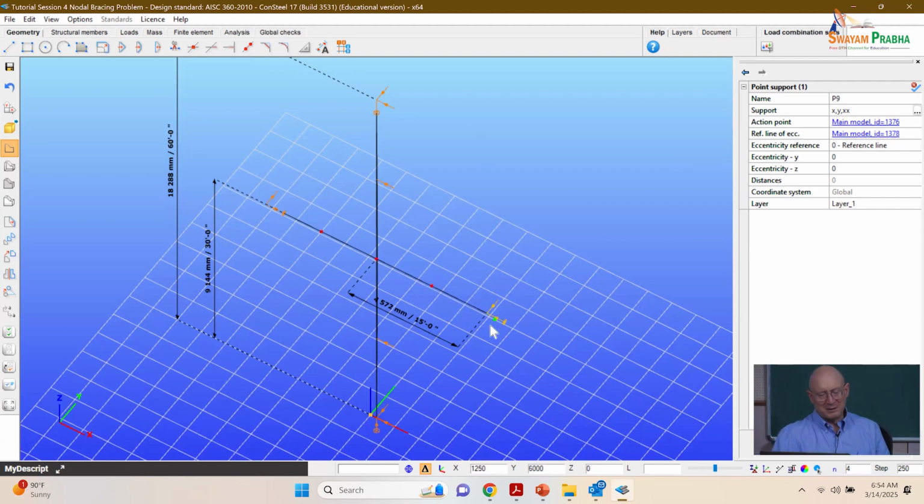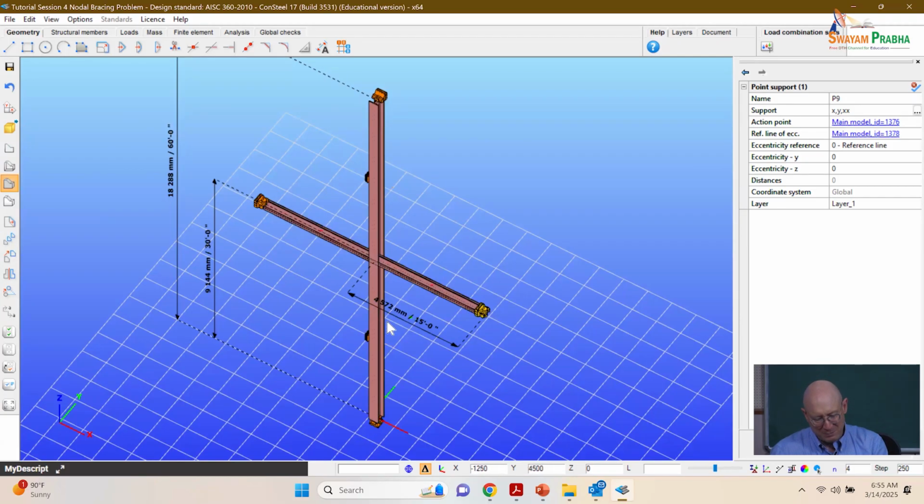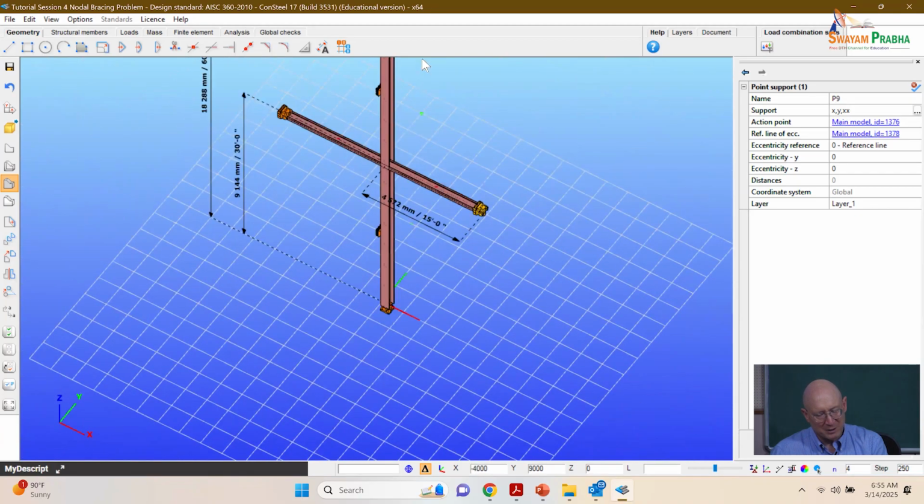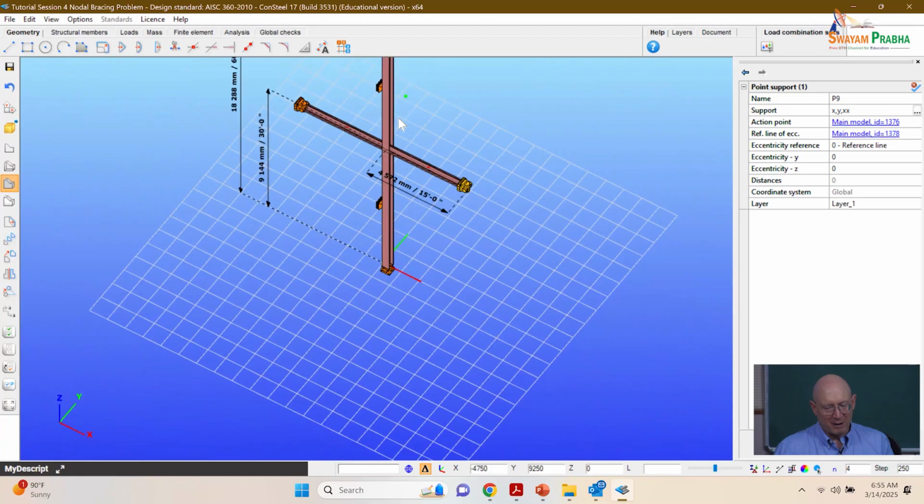The reason for that is if I restrain the Z, then when the column shortens, I would get some weak axis bending in this flying beam. So we're looking to do an idealization where we're not producing bending in that beam. Here again, the beam is in strong axis bending in terms of supporting the column, buckling major axis bending in the direction normal to this side of our shaft.